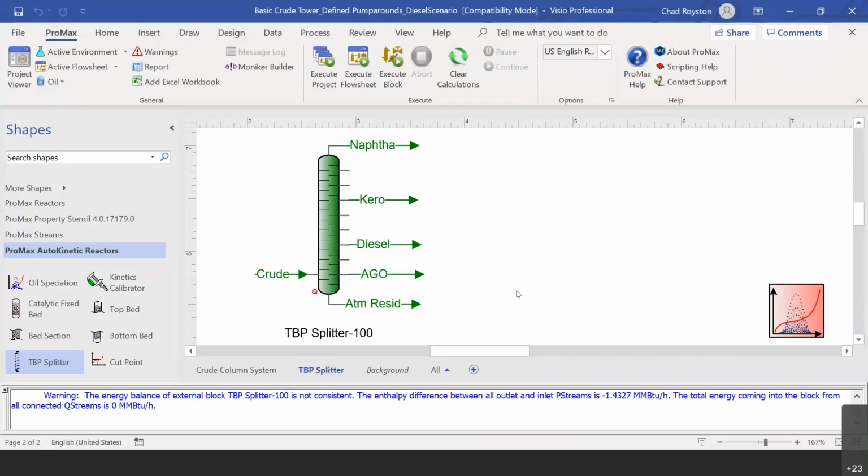How can we make a good estimate of the real yields? Well, that's a great point. What's important is to understand an approach to theoretical yield. Depending on the process, it can be a very handy tool. We're using it for crude here, but it can be used for stabilization. One of the best uses I see is reformate stabilization, where you want to drive off C4 minus, for example.